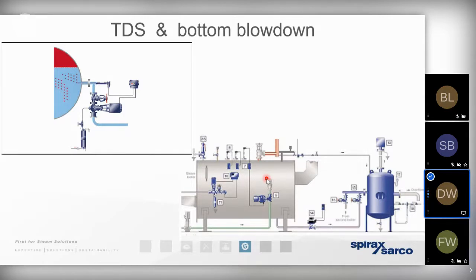You'll remember that an excess of foaming, especially when it's drawn out of the boiler into the distribution pipework, can result in an excess of scale. And that scale is not only going to contaminate the steam, it's going to make the steam wet, where we know we've got less energy present within the steam. But that dried out scale can also bind itself to heat transfer surface areas, and it can also cause a significant amount of erosion of those sensitive areas in control valves, flow meters, and so forth that we've spoken about.